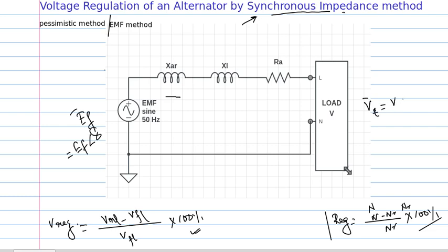It is equal to V angle 0. Generally in power systems, the terminal voltage is taken as the reference phasor, so that's why the 0 is marked here. Now this diagram itself represents neither an alternator nor a motor. If we give the direction of the armature current like this, then it will become an alternator.